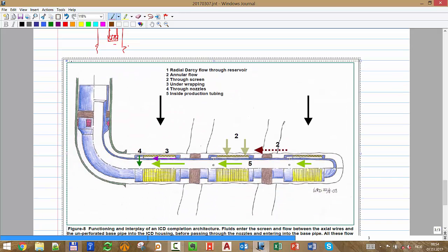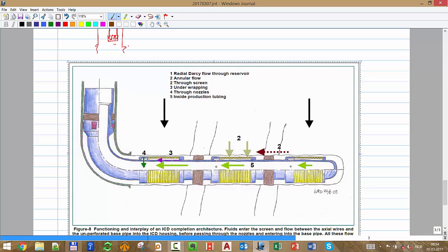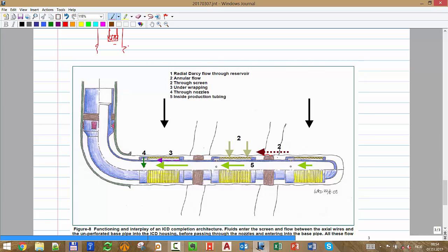You see, very nice hand sketch. So you have your packer at the top, isolating the production tubing with the casing, with the section, and then you have another packer. Usually these packers, if you have an open hole, are swellable packers that you almost inflate. It's like a balloon, okay? You inflate, because they have to have high deformation. This packer has a very low deformation. It needs that this distance will be very, very small from the beginning.